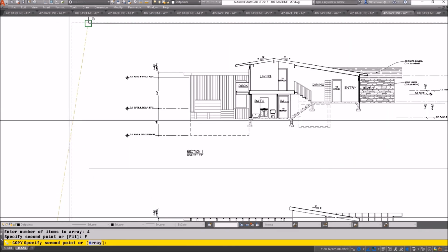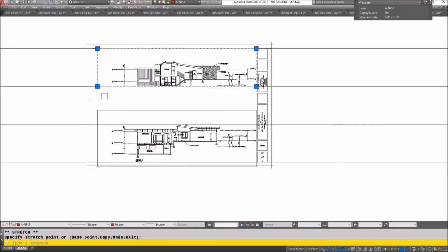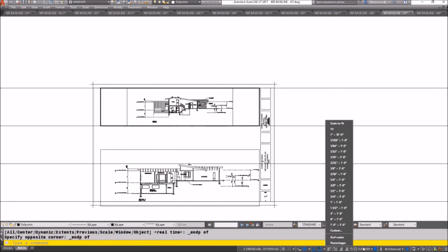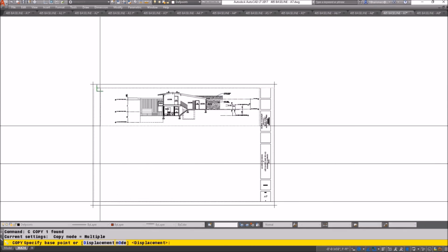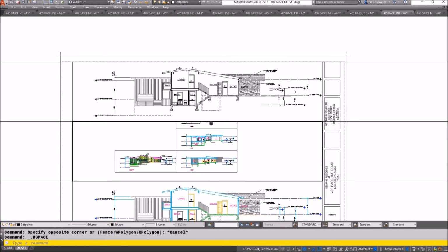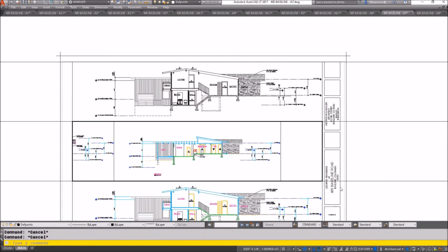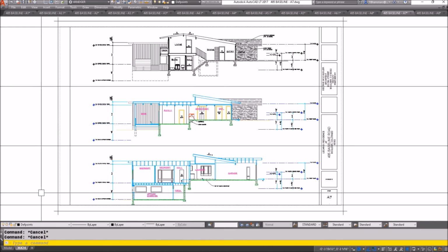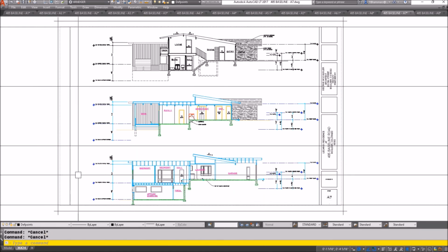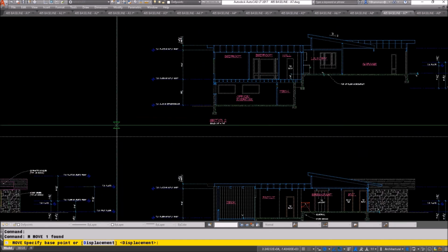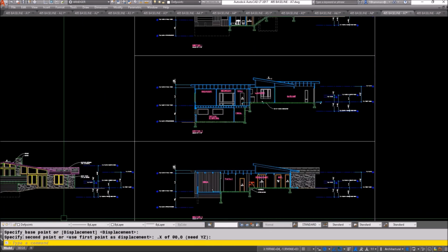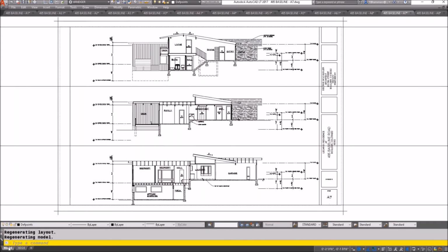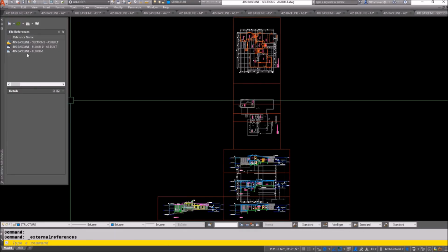So here's what I'm trying to do. I'm trying to get 3 drawings to fit, because I have 3 as-built sections and 3 proposed sections. So I just divided this up in thirds by using the array and then doing 4 and then saying fit, and made it into 3 sections. 4 lines, 3 sections. And then I just zoomed those up to 1/4 inch, so I got them all to a line. That's why I draw frames around stuff that I draw, because that's how I reference everything and make it nice and clean. It gives good continuity. And I did the same thing for the proposed elevations.